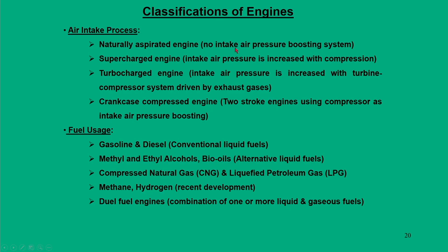Then the classification goes in another direction as well, the air intake process. The engine requires fuel and air. Now if you talk about the engine with respect to air intake, how air enters the cylinder, in a normally aspirated engine, that means a normal engine where there is no boosting of air, it comes in on its own through the air intake or air manifold. So, it is a naturally aspirated engine.